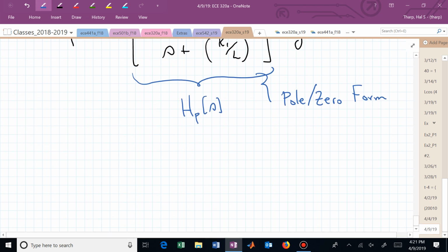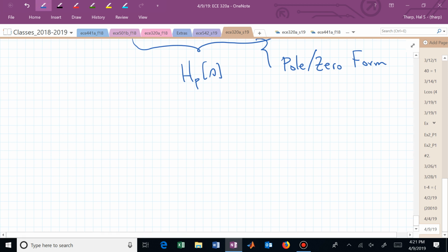Meaning, the magnitude plot of this is coming up from the basement, and this upward slope is due to a 0 factor, and we had a 0 at the origin. And how fast are we coming up?